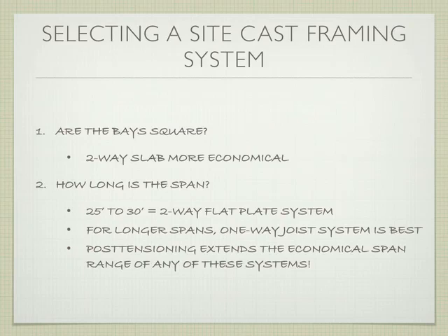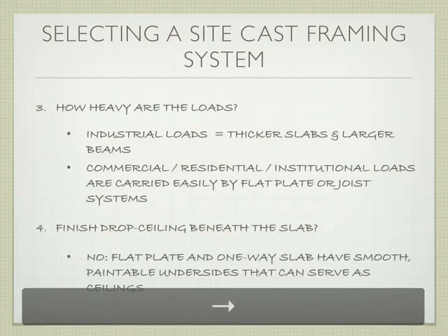If it's post-tension? Well, on a two-way system, you're going to max out at about 30 feet. If you add the post-tensioning in, if my memory is serving me correctly, which I should look up just to double check, it's usually a third longer. So we go to 45 feet. But again, it depends on the engineer and the calculations and stuff. And I should double check that number because that's off the top of my head.